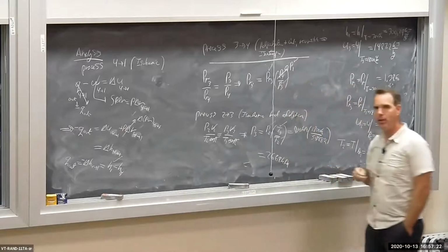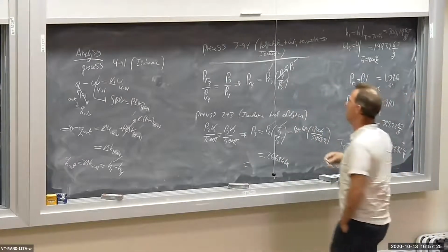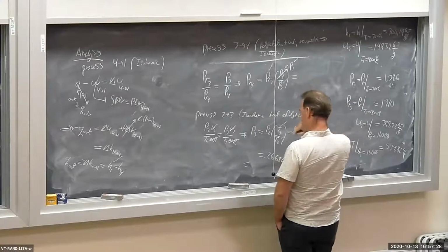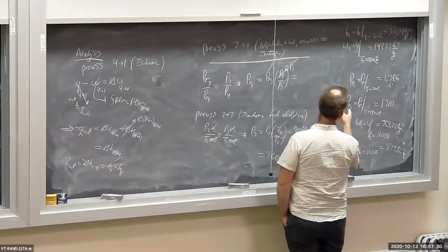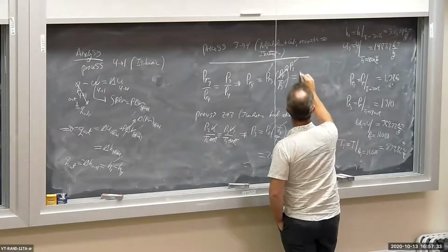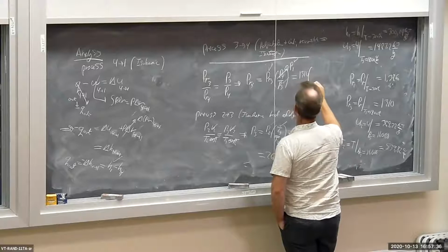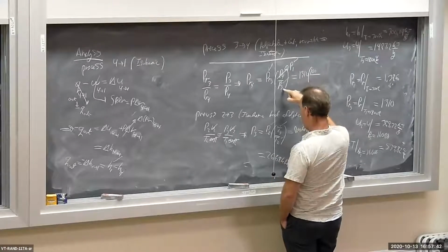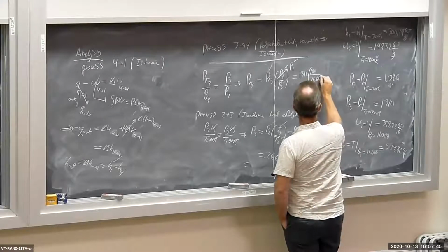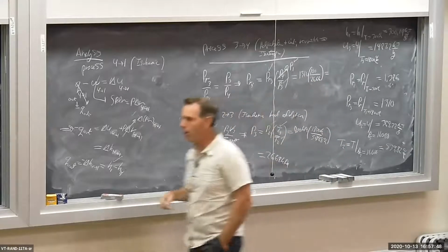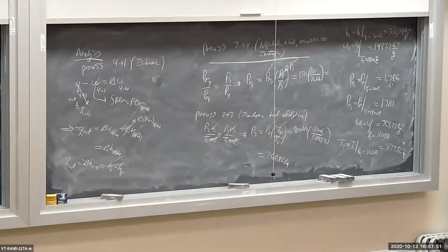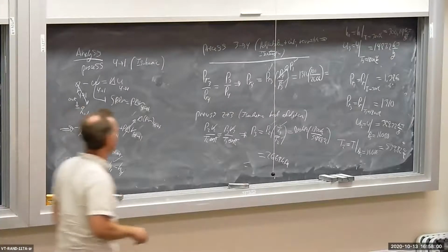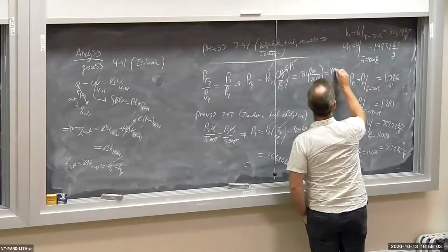Okay, now I can get PR4, so I can get H4. Let's see here. PR3, 1310. P4 is equal to P1, and that's 100 kPa. P3 is 2668 kPa, and I get a PR4, reduced pressure at state 4, of 49.1.